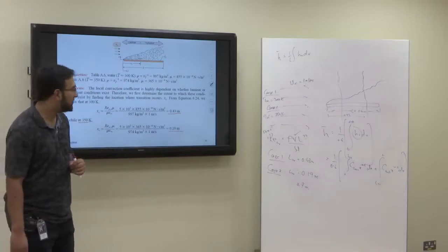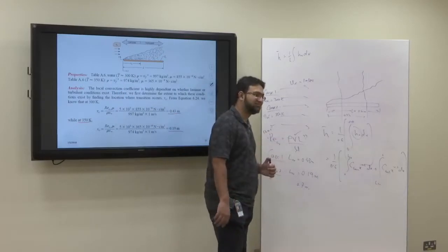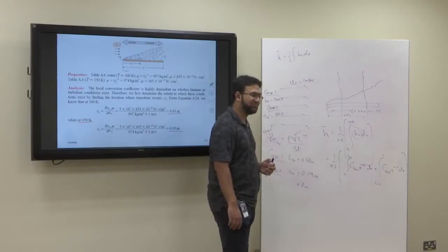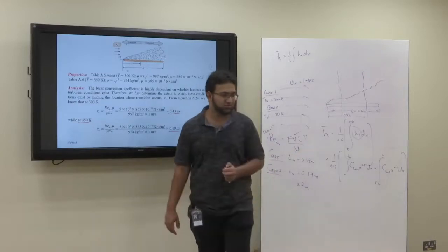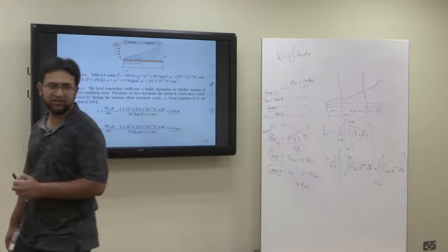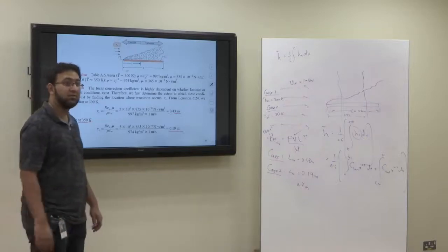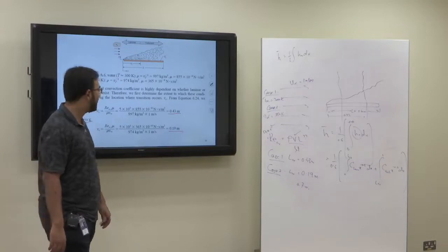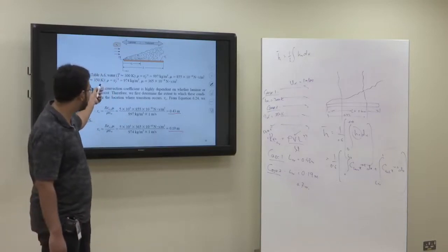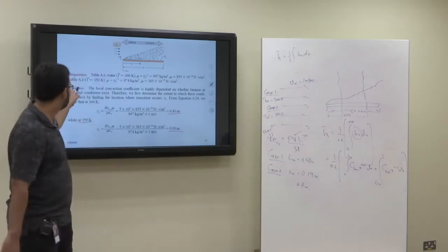When you try to find the properties of water, finding density would be interesting. You have the property table with you? Can you find the density of water at 300 Kelvin or 350 Kelvin? I think the density of water is not steady. It was 1000 every time, but it's a function of temperature. Temperature here is 300 Kelvin. It's written here, use table A6.